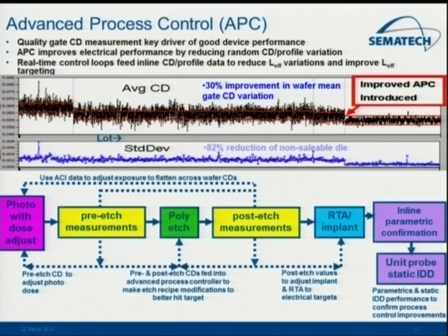And what that really means with regards to your control is, for example, if you're measuring this critical dimension, this line width, and you introduce the APC, you can significantly tighten up the distribution of your measurements post-etch in this case. In this case, you can see about a 30% improvement. That improvement with the average CD and the targeting plus the distribution of those lines means that the key thing you're doing this for is you have more of your devices that are in specification, and you can sell more or sometimes charge more depending on what that business model is like. So this is a direct example of why you would use advanced process control, because you can actually make more things that you can sell.